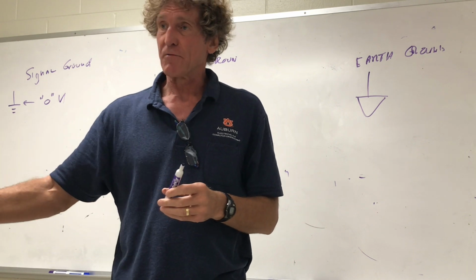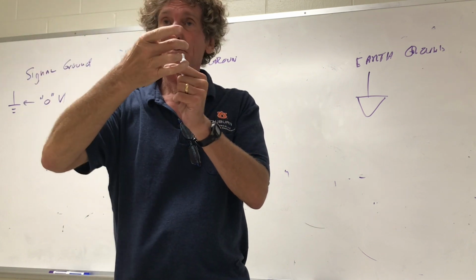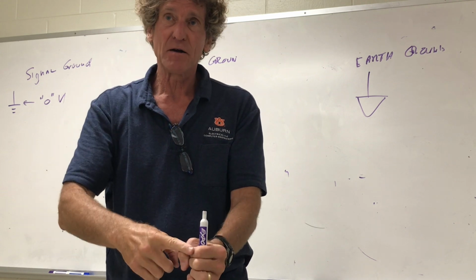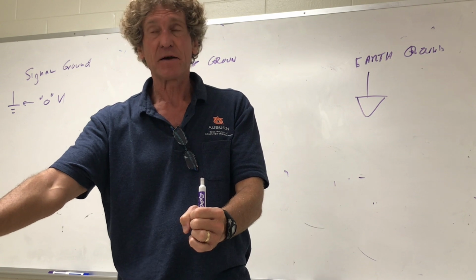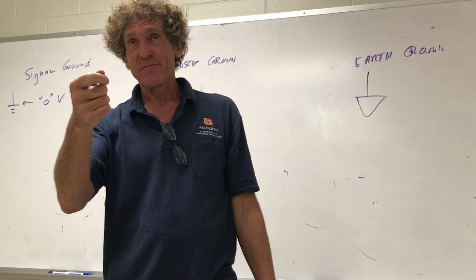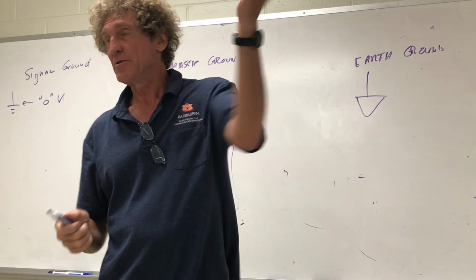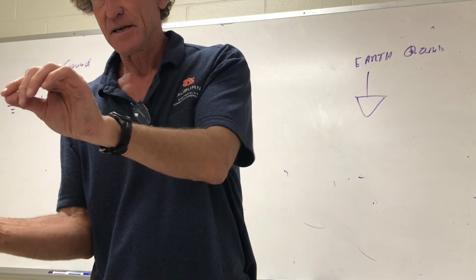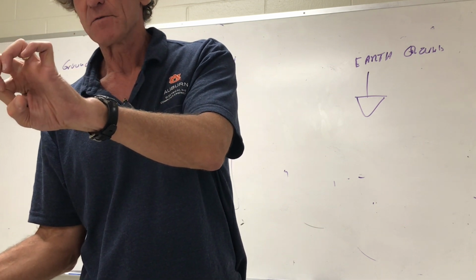So we took a grounding rod, one of those, and we bent the tip into a hook. And then we took that rod and we used, I think it was 4-aught wire, it might have been 2-aught wire, and we had this hooked to the actual earth ground of our building over there. And so when we wanted to discharge them, now this is one of those things, you can't just put it across there and get a huge amount of current. So in series with all this, right after the chicken stick's connection between the 4-aught and the big thick ground rod, we had something called a water resistor.